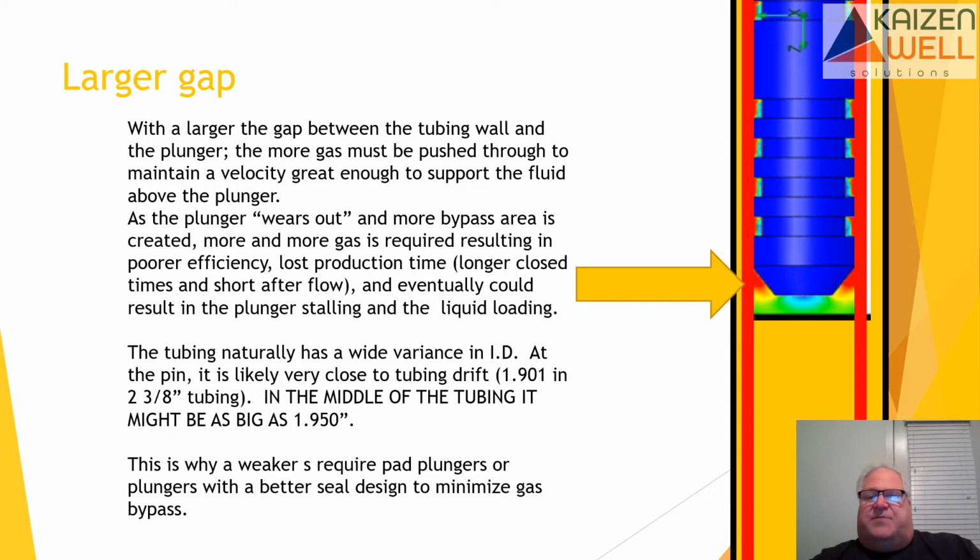Some wells that can be 5,000, 10,000, 15,000, 20,000. I've seen plungers run on wells that are worn out to where there's almost no ribs, and the wells are doing fine. It's just that strong of a well. But one of the easiest ways to figure out when you should replace that plunger is your operator should be carrying some plungers in their trucks. And every month or so, they should go out there and look at a couple of wells and drop a plunger in and look at the production yesterday and the production tomorrow.